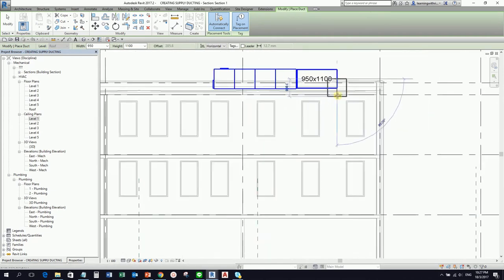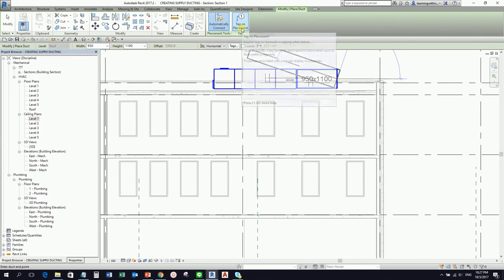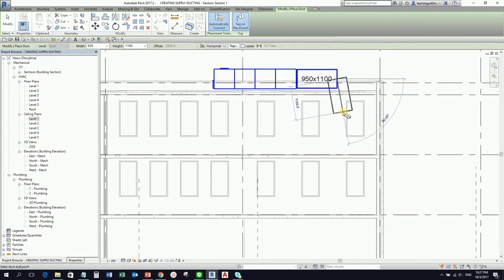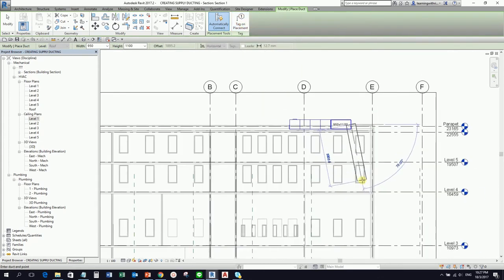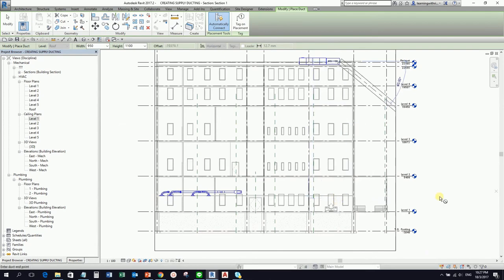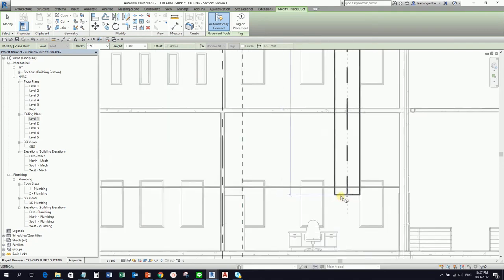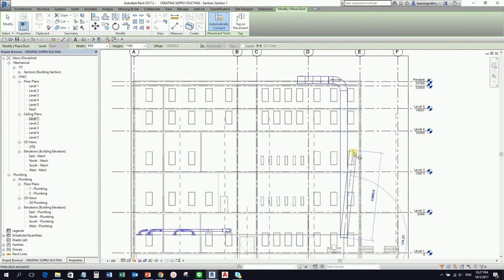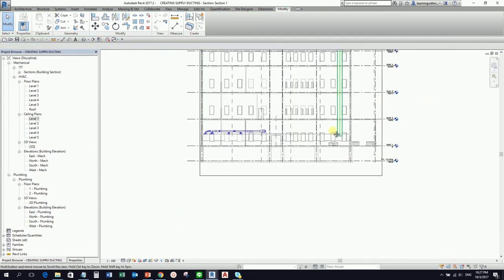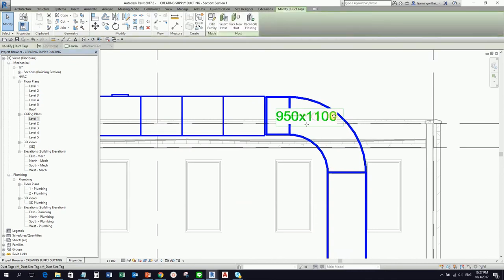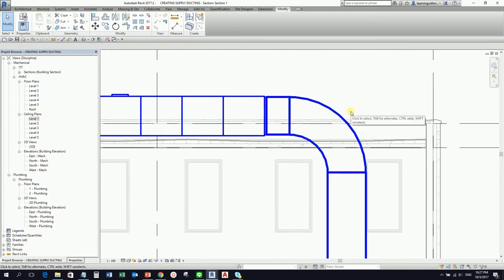Alright. The reason why there's a tag every time I create a duct for this particular equipment is because this is turned on. If this is turned on, it automatically places the tag. If I turn this off, toggle off, then as you can see, if I create the duct, let's say somewhere here, you will notice no more tag, right? So I'm going to select modify. Then I'm now going to remove this one. I'm not going to tag it yet, so I'll just delete that one.